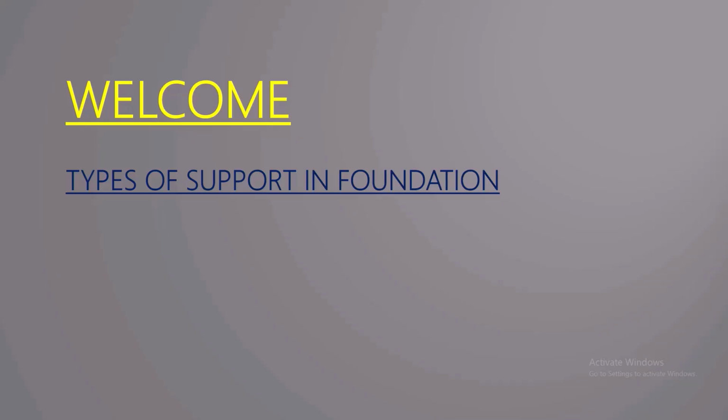But in all your design, is your foundation actually fixed support? So you see that when you know these types of support, you're able to have a realistic design by modeling the right support, not always the fixed support that we do model.